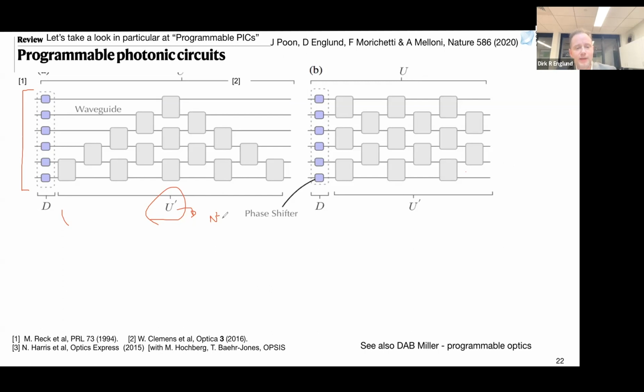And so you will already say, hey, in your project, you said you wanted to do 1,000 modes. And that wouldn't work because 1,000 squared is 1,000,000. You can't have 1,000,000 phase shifters. And you're right, we couldn't get 1,000,000 phase shifters. We did the best that we could with spatial mode encoding, putting n up to about 20 or 30, and then used other degrees of freedom, namely frequency, to encode the other degrees of freedom. But anyways, this is just how we ended up going in the direction of these programmable optical circuits.